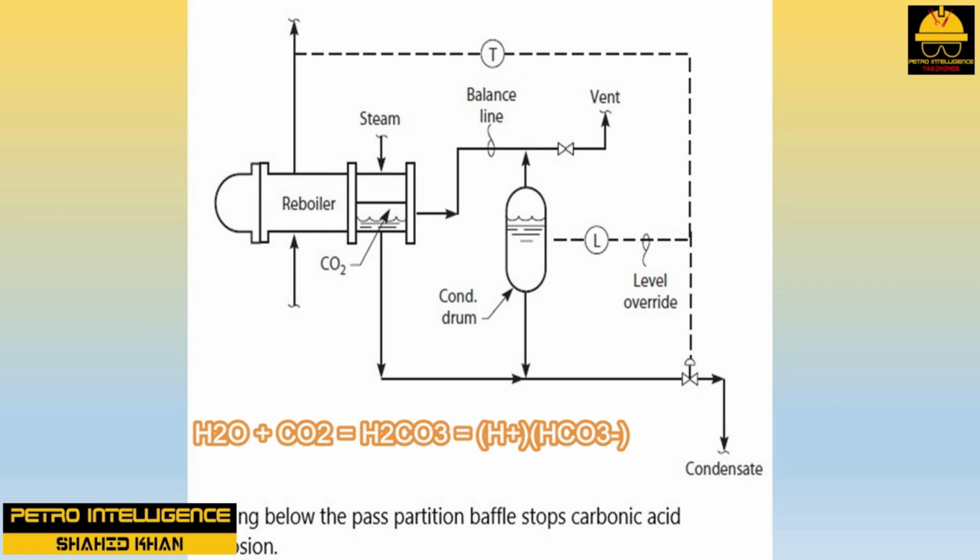This is done by continuous venting from the top of the condensate drum. For every 10,000 pound/hour of steam flow, vent off 50 pound/hour of vapor through a restriction orifice placed in the condensate drum vent. This is usually cheaper than controlling reboiler steam side corrosion with neutralizing chemicals.